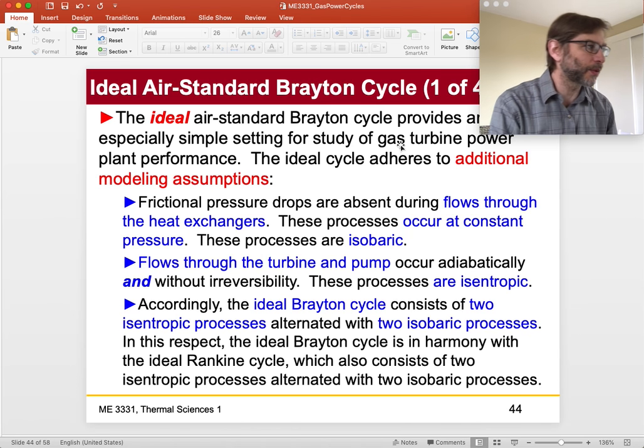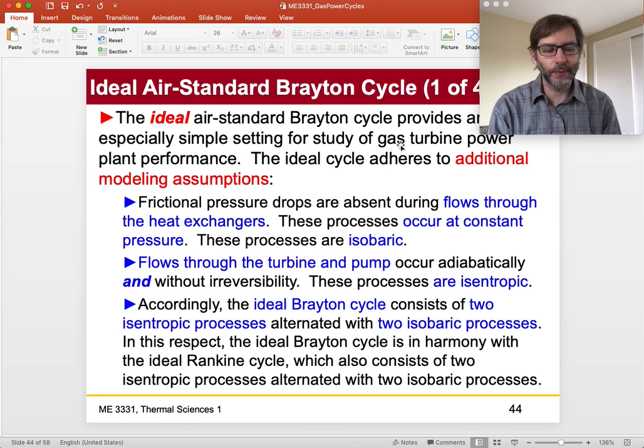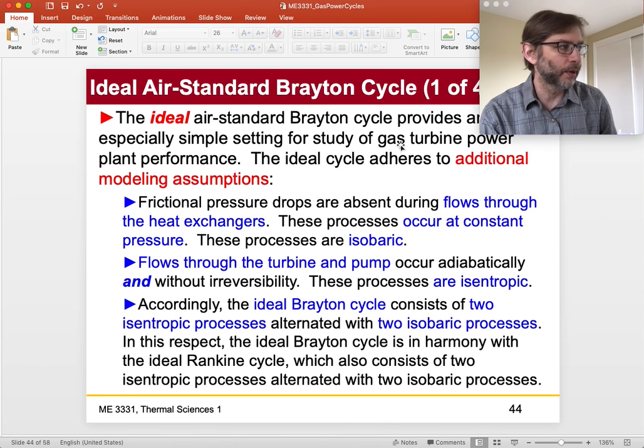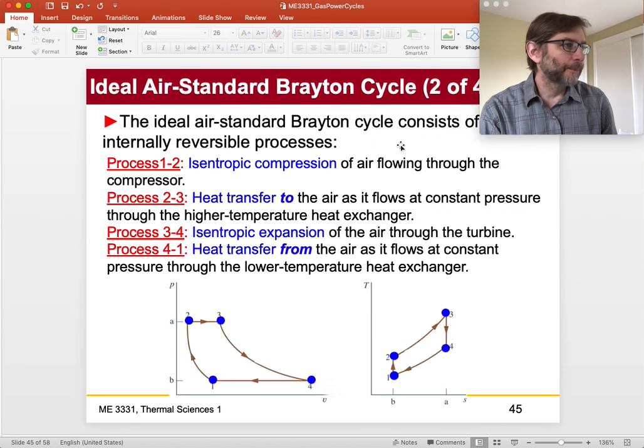So they're isobaric in the Rankine cycle too. They're mostly isothermal, but because they go across the vapor dome, they're isobaric and isothermal for a proportion, except for the boiler, which we've discussed.